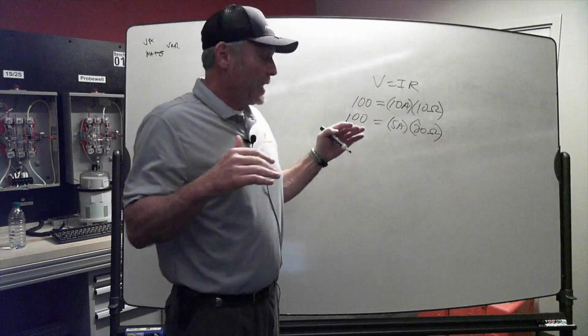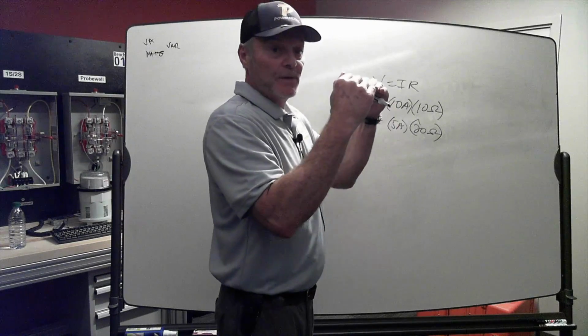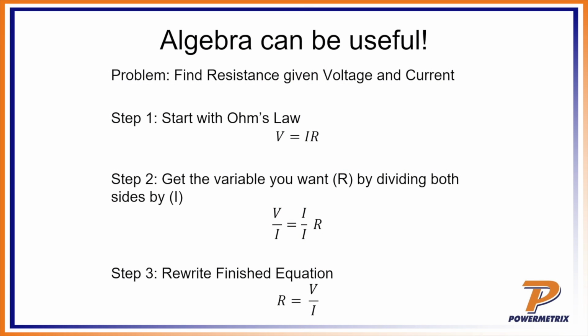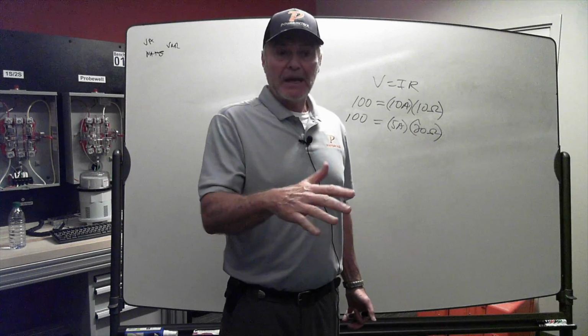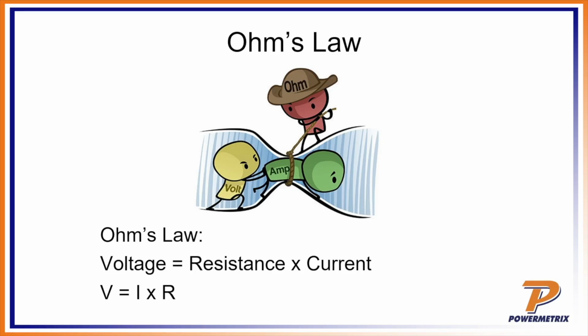And we've seen the picture, and we know how that goes. If your resistance goes up, your current comes down. So you remember on the picture that we saw just right before this, you can see it's choking it in that the ohms up there, the resistance, dude in the hat. As he's choking it down, you get less flow of the amps or current through there. So that's exactly what happened in our equation too. As my resistance or my ohms goes up, my flow of current comes down. We a lot of times use the flow of water in a pipe to talk about electricity. So here you can see that an increase in the resistance chokes my pipe, and I don't get as much flow through it, okay?